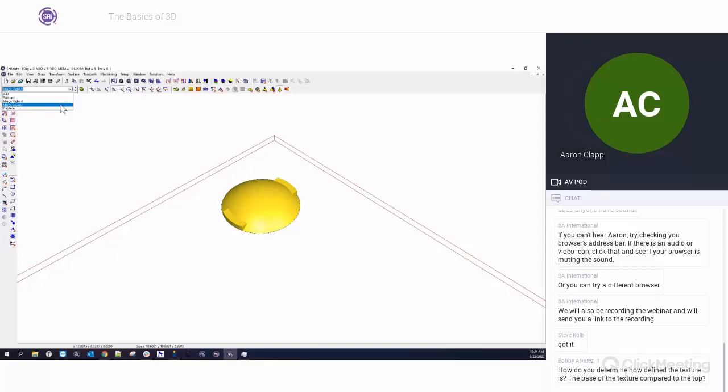So now merge lowest basically does the opposite, and it says, okay, whatever the lowest relief is, use that instead. So in this particular case, what it did is it cut out the top of the circle right here where that flat spot was, because that was actually the lowest relief of the two. And out here, it didn't, because the relief didn't intersect.